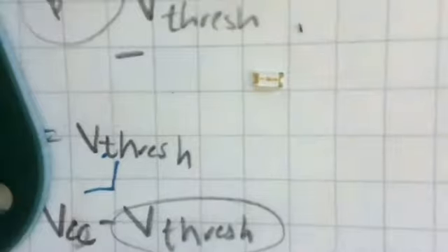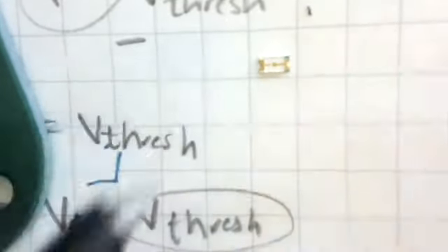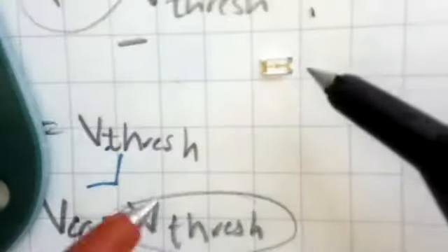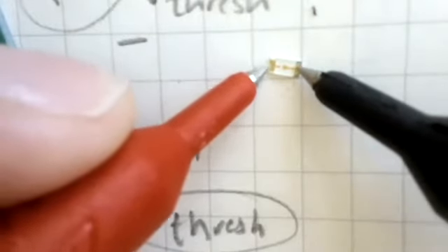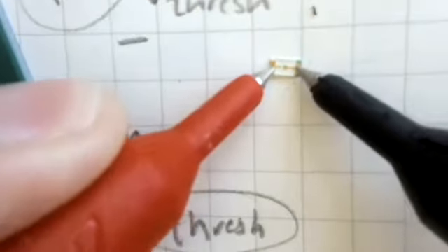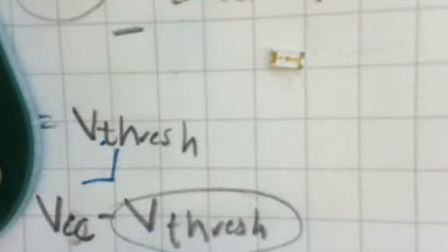And what we'll see is that if we hook the pins up to the diode in the wrong configuration, nothing happens. If we hook them up in the right configuration, so with black, which is connected to the common or ground input on the multimeter, and red, which is connected to the positive one, the diode should light up and it should work. But okay, it doesn't because I haven't pushed the select button on this multimeter.